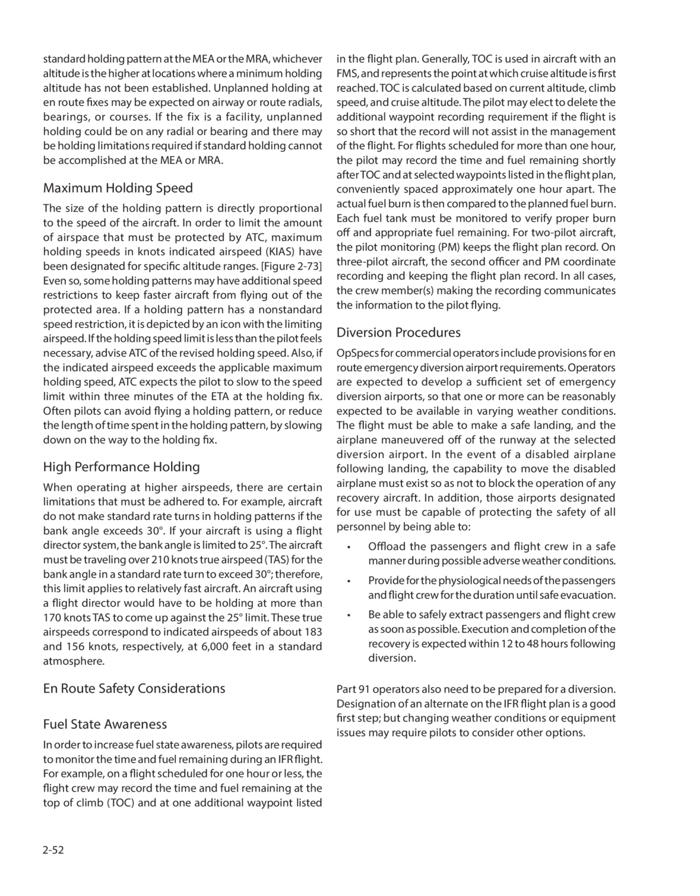For flights scheduled for more than 1 hour, the pilot may record the time and fuel remaining shortly after TOC and at selected waypoints listed in the flight plan, conveniently spaced approximately 1 hour apart. The actual fuel burn is then compared to the planned fuel burn. Each fuel tank must be monitored to verify proper burn-off and appropriate fuel remaining. For 2-pilot aircraft, the pilot monitoring, PM, keeps the flight plan record. On 3-pilot aircraft, the second officer and PM coordinate recording and keeping the flight plan record. In all cases, the crew member making the recording communicates the information to the pilot flying.